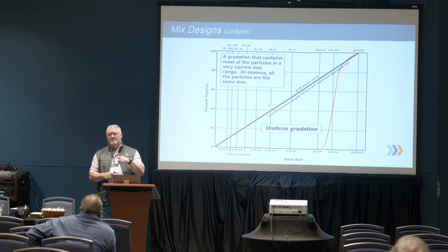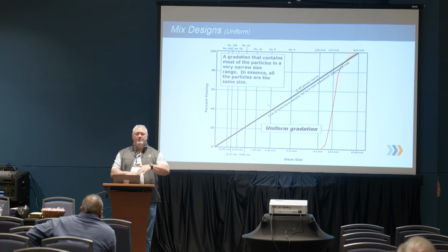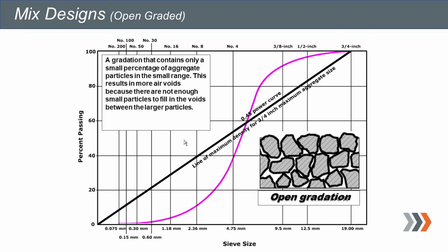Didn't do any densities, but at 8 inches, while we tested it, we had the fire truck come out and spray down. If it drained, great. If it puddled anywhere, we had to remove and replace it. Then they put 12 inches of concrete over top of it. So good drainage base. Open graded friction course, we can use this as a great drainage base as well too.